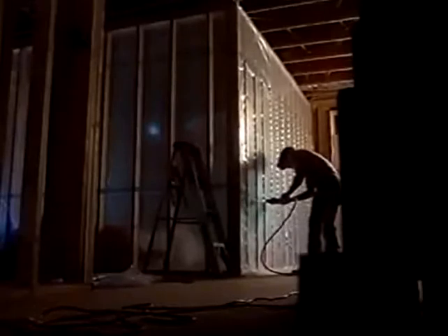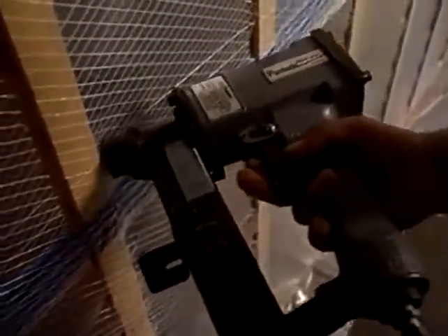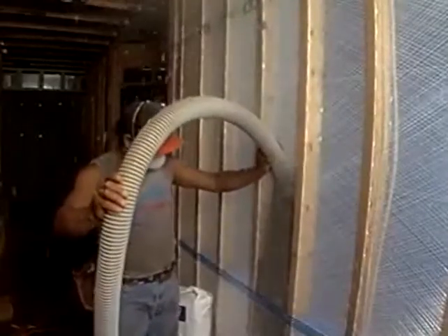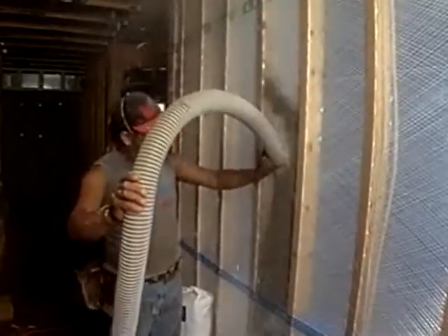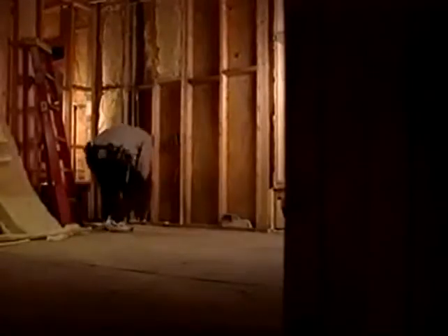Installing insulation without a proper air barrier means unwanted air will leak into the living space and can cause comfort problems for homeowners. Mistakes happen in every building we build. They're not intentional, but every one of the trades should be trained so that they can spot what makes their product not work as well as it should. As an insulation and air sealing specialist, it's your job to spot breaks in the air barrier and seal them.